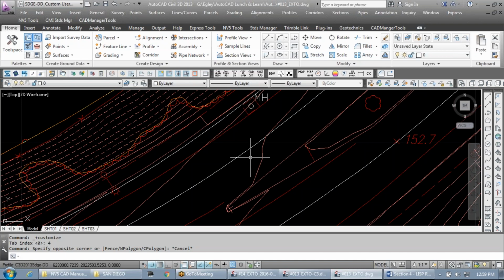If it's a detail, your detail may actually have separate text than what you're showing in your plan view. So yeah, you wouldn't want that to be annotative because you're going to freeze it in one viewport and keep it at this other detail viewport. So just kind of keep that in mind. Just be aware of your annotative text. Don't create annotative text if you're not using it for different scales. It bloats your files, right? Because it's then sizing that text for every viewport. It's going through all those processes. So just be aware of how you're using annotative text. All right?